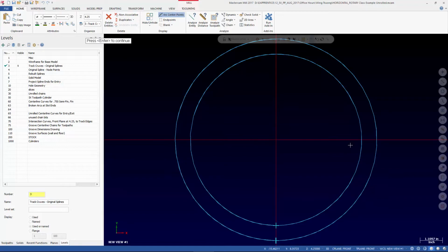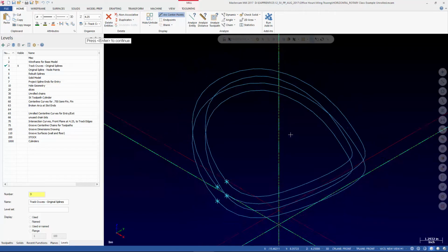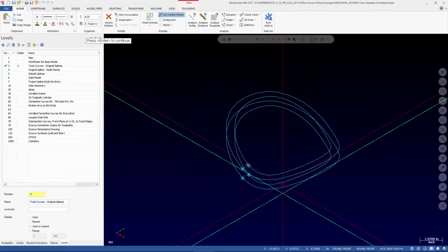So here, when we look from the top view, I've rotated the part 90 degrees, and that means the start and stop position of those tracks is now aligned with my spindle, since I'm using a horizontal machine. So this is going to be B0, which means that if I were to cut this, I can start at B0 and I can rotate positive or negative 360 degrees and come back around to the same end.